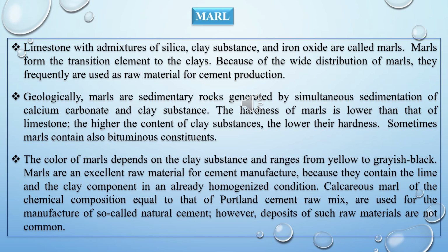Now the next point is, geologically, marls are sedimentary rocks generated by the simultaneous sedimentation of calcium carbonate and clay substance. The hardness of marls is lower than that of limestone. The higher the content of clay substance, the lower the hardness. Sometimes marls also contain bituminous constituents.